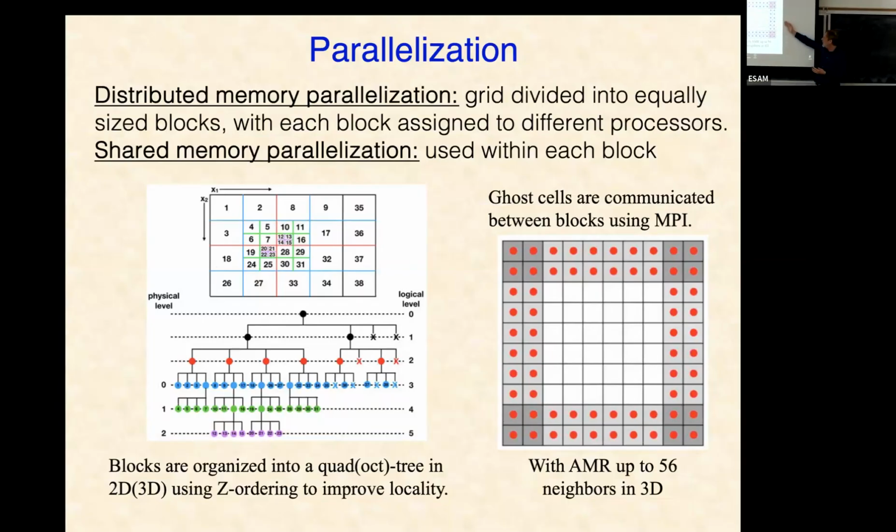And so whenever you have a fine mesh touching a coarse mesh, you would pass not only the data, the cell-centered values, but also pass the fluxes at the edge, and then use the fine fluxes to update the coarse cells on the coarse mesh, right? So does that mean you add the fluxes basically, like if you have two fine ones next to a whole one, and you add the two fluxes? Exactly. So that the total amount of flux of everything is conserved across.